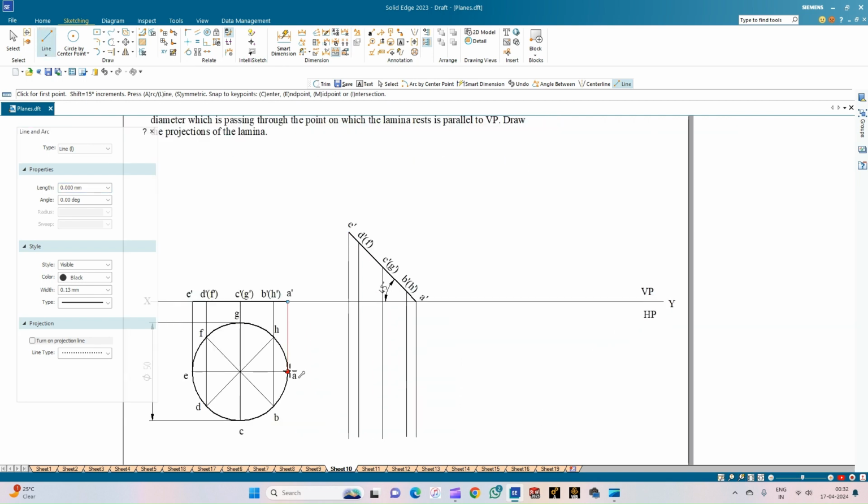and we shall draw the horizontal projection lines now. So from point A, intersect the projection from point A. Similarly, from D through B, intersect the projection lines of B and H. Similarly, from C and from E to A, it is already done. So F to H, so intersect this, and from point G, intersect the projection from G. So we have got these points.